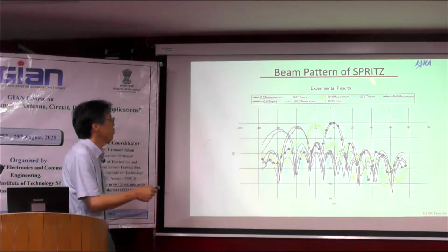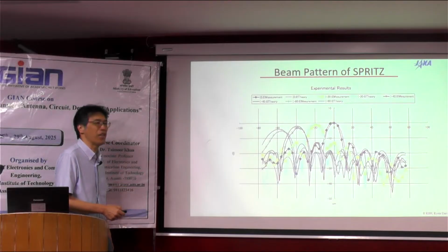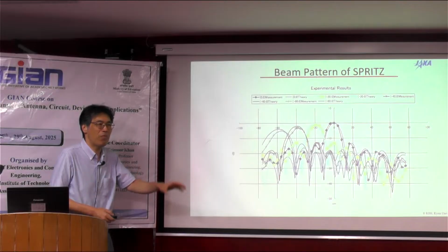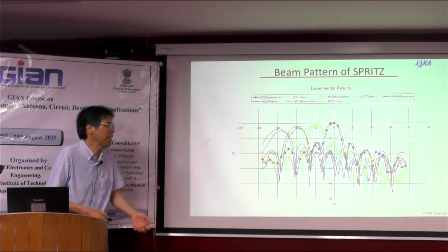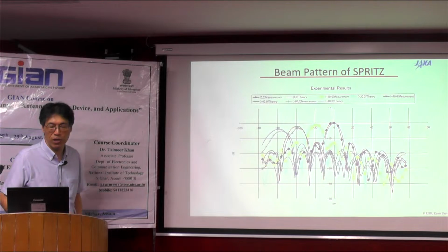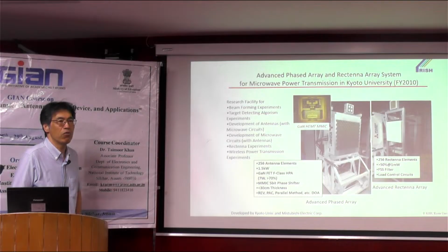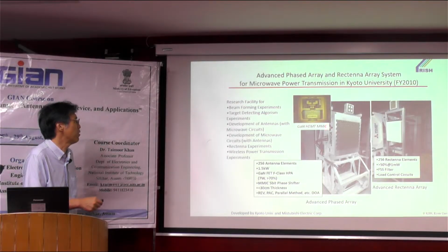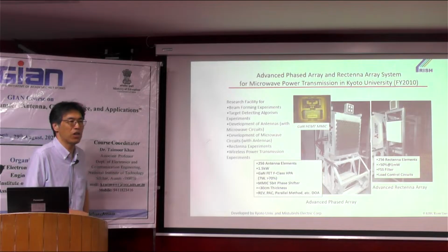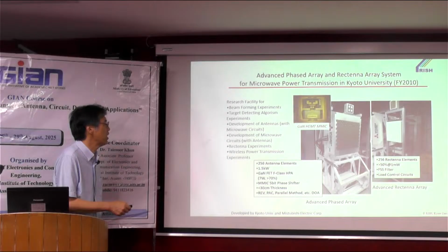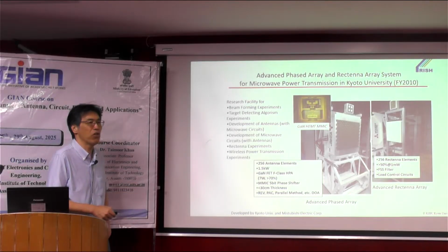In this SPS, efficiency was bad because we installed a very high power amplifier, and after the high power amplifier, we installed a lossy phase shifter. But this is a very good demonstrator of the solar power satellite. And about 15 years ago, we, Kyoto University, got a very huge budget to develop gallium nitride semiconductors. With help of Mitsubishi Electric, they developed a good gallium nitride semiconductor, and we could develop this phased array antenna with newly developed gallium nitride MIC.